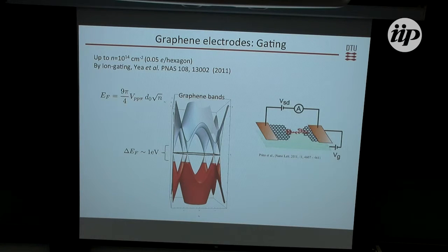And one very interesting thing when it comes to the electronic structure of graphene is that you can tune the Fermi level of graphene quite a lot just by a gate. Compared to metals, where the Fermi level is completely fixed, here you have this high tunability, and you also have that for other 2D materials. So for that purpose, it's very interesting to use. People are now thinking about using graphene to contact other 2D materials, or even single molecules, so you can control the transport with a gate.